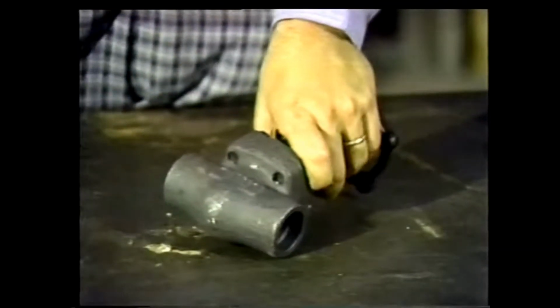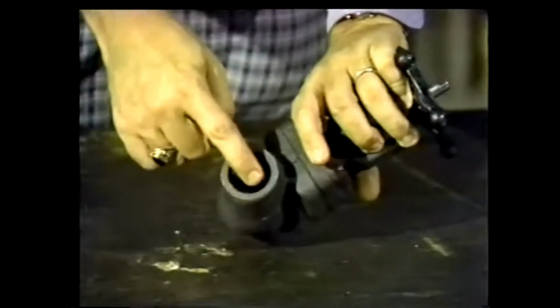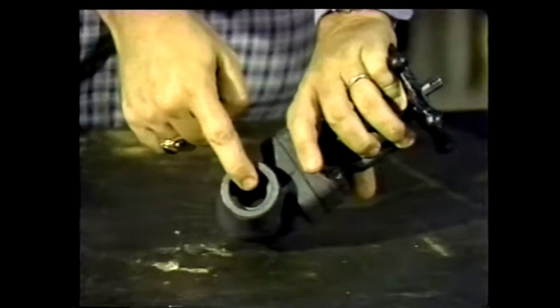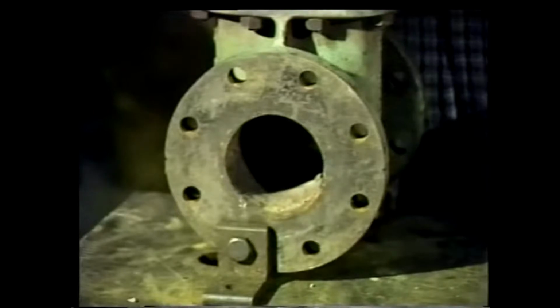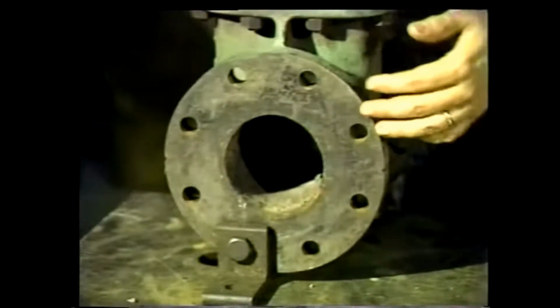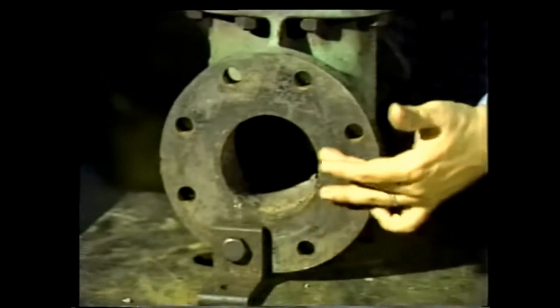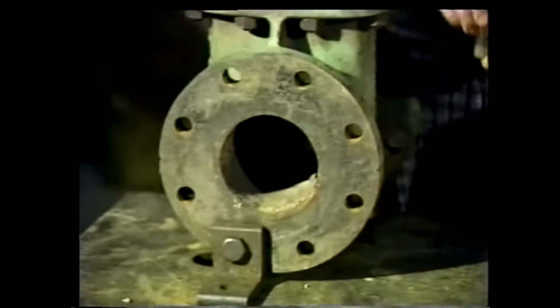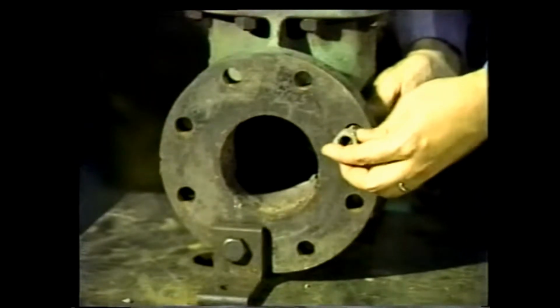When they're to be welded in, the inlet and outlet stubs of the valve body are smooth and ready for welding or brazing. Now, brazing is similar to welding. The valve can be brazed using a standard brazing rod. The flange is another common type of connection. In this case, the valve is bolted in place, and the inlet and outlet stubs of the valve are flanged like this to allow for bolting with system piping flanges.